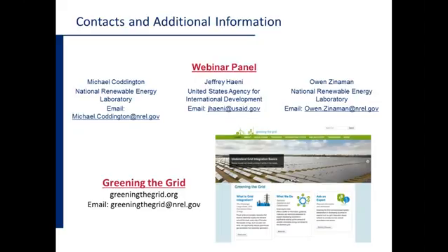A minimum bill is a tariff component that doesn't change the rate components of the standard bill, but instead specifies a minimum amount that a customer will owe in each billing cycle. If they happen to get to that minimum bill through buying kilowatt hours, if they're net consuming that month, so be it. But if they don't, then they're still hit with that minimum bill to ensure that the utility recovers its fixed costs.